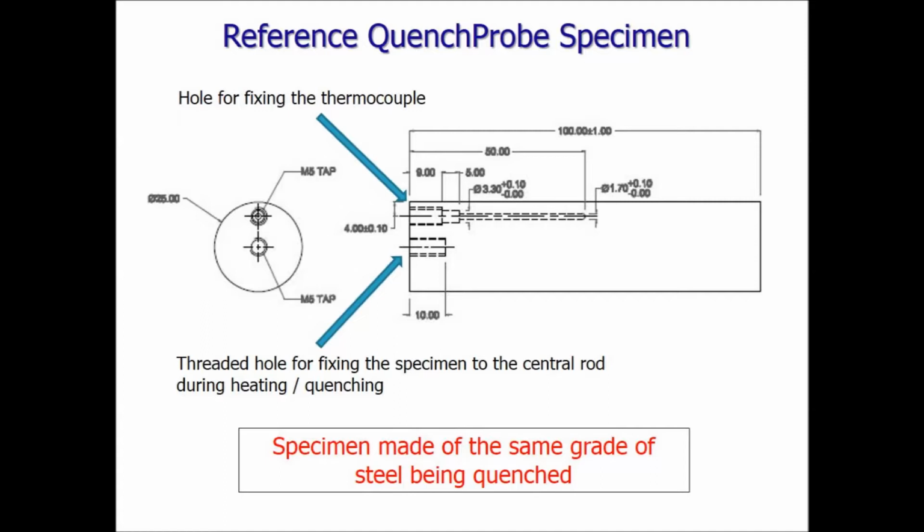And on the quenching side, the agitation in the tank, the usage factor of the oil, and a host of other things which are not considered during laboratory generation of the cooling curve.